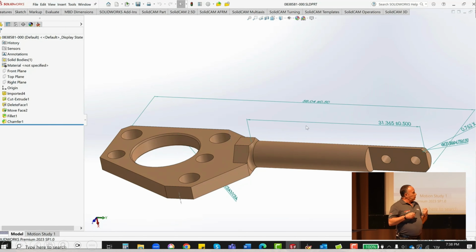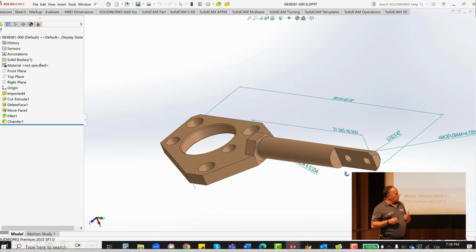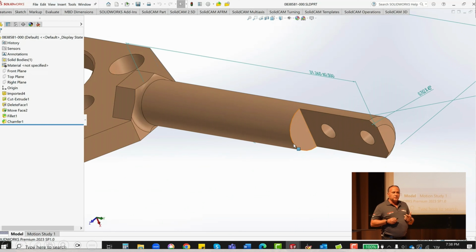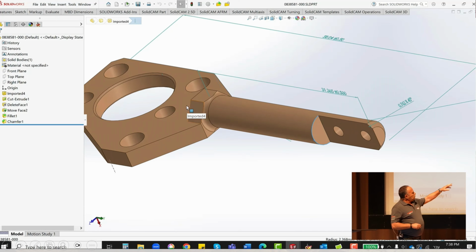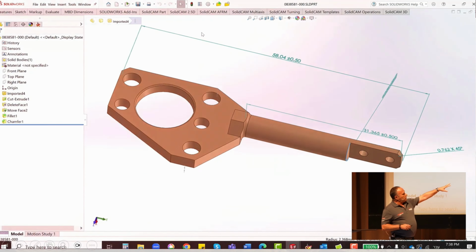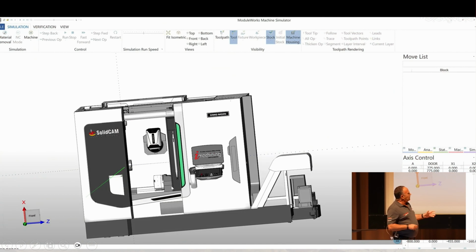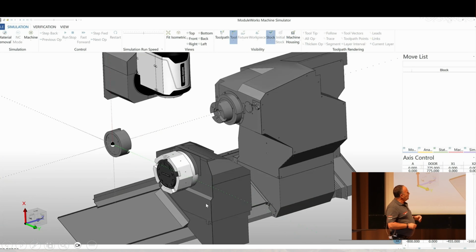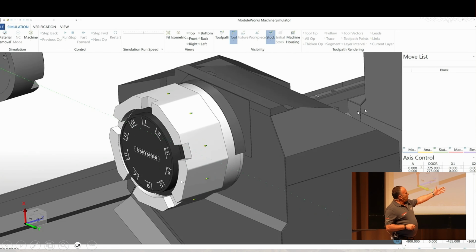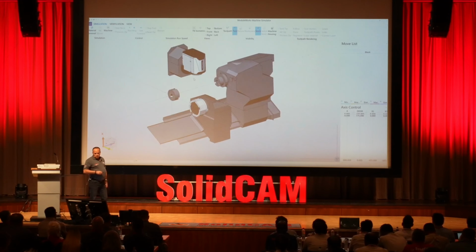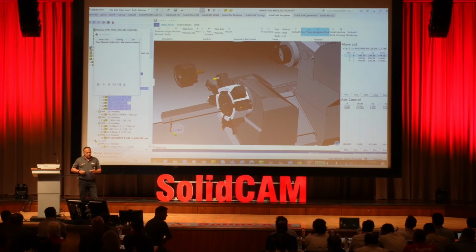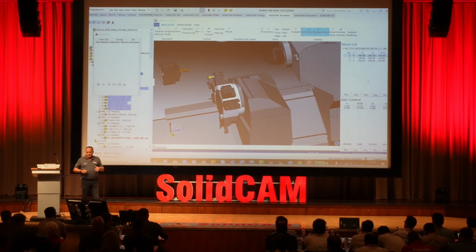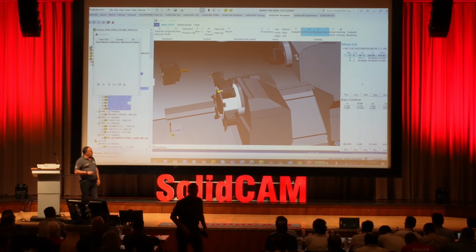combines the powerful functionality of SolidCAM with the CNC technology know-how of the factory. As we can see here, there is a very small diameter, smaller than 3 millimeters, along 32 millimeters of the bar. It is programmed to machine on a DMG Mori machine, with back spindle, main spindle, upper turret, B-axis, and lower turret. And we will jump directly to the machine simulation.